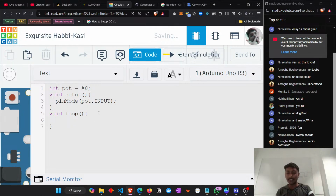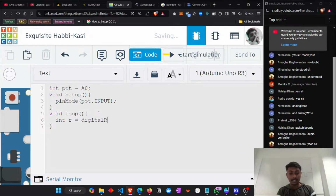Now we will be reading it. To read, I need to store it somewhere. I can't just read and throw it, right? I need to read and store it. So I will take int result or r. Result is equal to what? digitalRead, right? D-I-G-I-T-A-L, digitalRead. R is capital. R is read. Now digitalRead is what? Which pin am I reading? Pot. Pot I am reading, right? Now I have read everything.